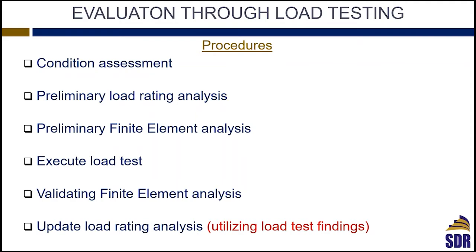What elements are the deficient ones that we are going to go and test in the field? After that, we start with our preliminary finite element analysis. We develop a detailed model, as we will show later, and then go to the field to do the load test, then come back and validate our finite element model, and then finally update the load rating analysis based on the findings from the field test.